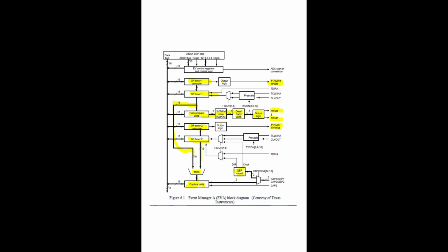As already told, this QEP circuit is used for digital motor speed sensing, and it converts that speed into multiple pulses, which are given as input to the timer.